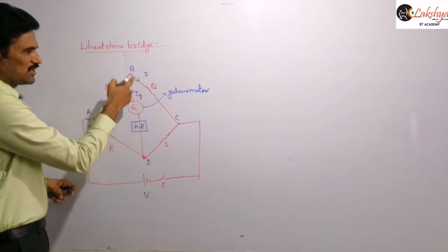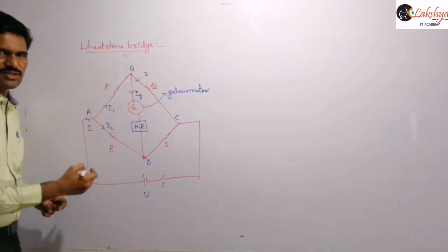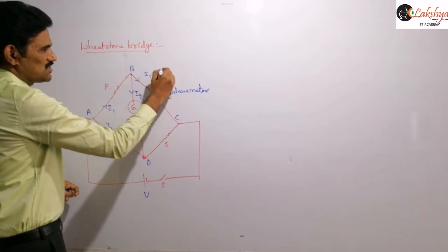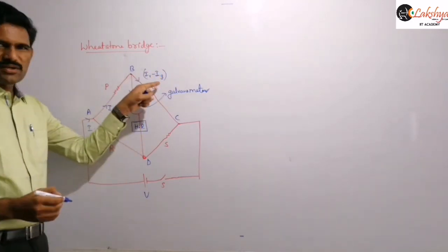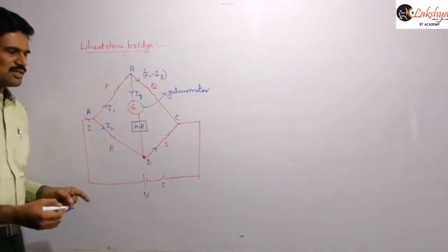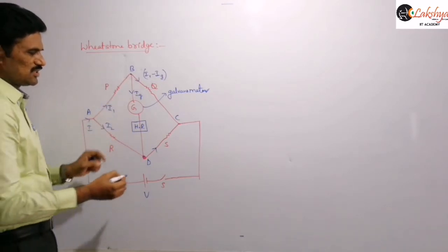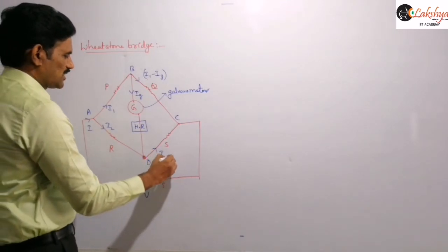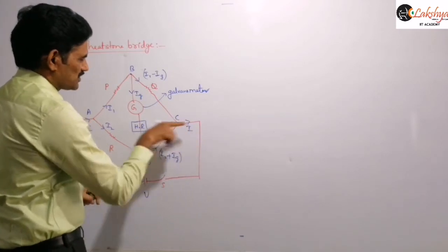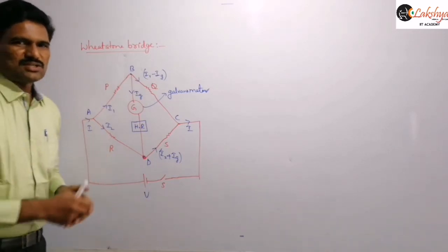I am applying the Kirchhoff junction law directly. I1 is reaching this junction, out of that Ig is flowing along this direction. So the current in this direction we can write as I1 minus Ig, right? Similarly, along this direction, I2 is flowing like this, and then Ig is reaching the junction. Both are reaching the junction, so I can consider I2 plus Ig. Then the total current I1 plus I2 you will get, which is I, that flows out of that junction. So that is the current distribution.